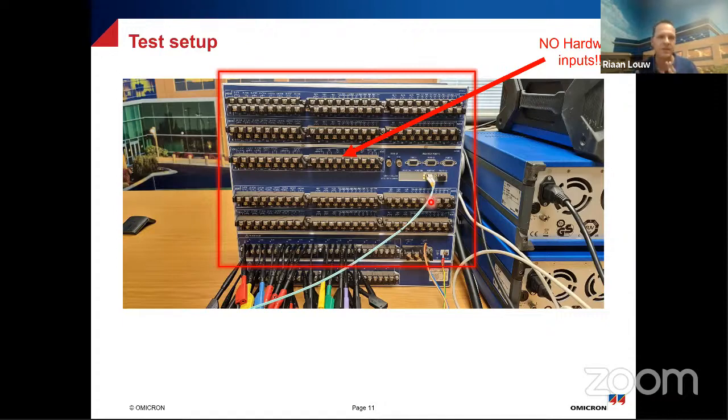Now, what RelaySimTest allows you to do then is if you have that GOOSE configuration as a test logic in the background or in parallel, then you can easily just move on from that and switch to that and test by simulating with RelaySimTest these GOOSE messages being published to the relay and the relay subscribing and switching automatically. So this can be done in a couple of ways.